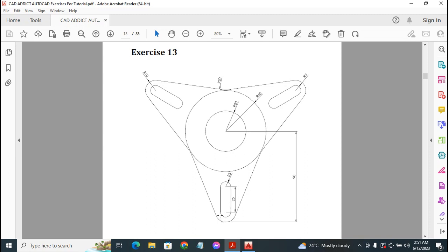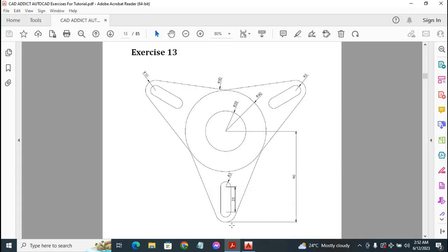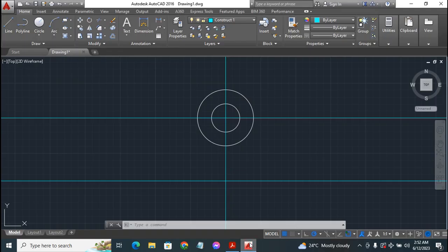If that is a 10 millimeter radius, that means we have a circle of diameter 20 millimeters. So we are going to draw in a circle right there. Next up, we want to locate the center point of this circle of 20 millimeters. So how do we do that? Back to CAD, right from this end, the very end of our drawing. Next up, we want to locate the center point of that curve.